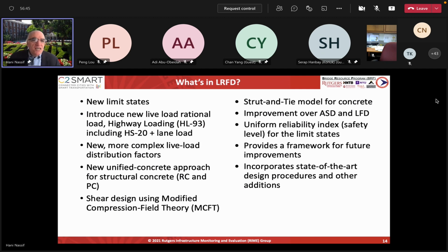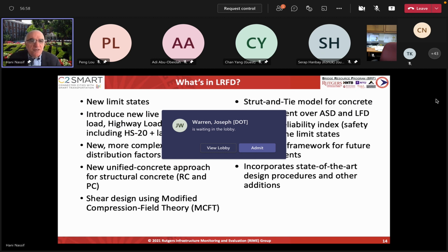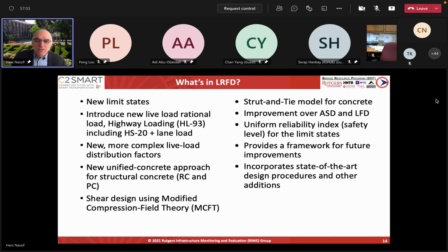So in a way, we needed something a little bit heavier, but to keep that familiarity, the same arrangements. And this is where I think Dr. Kulicki, with a combination of different loads, came up with what used to be used as a lane load. For those of you who don't know the previous LFD, they used to design bridges by using what we call truck load or lane load. The reason is because on long span bridges, many trucks will be in a traffic jam, and that represents a uniform distributed load.